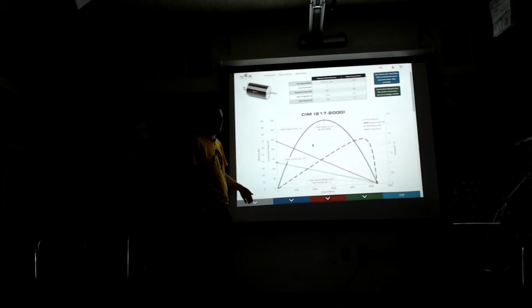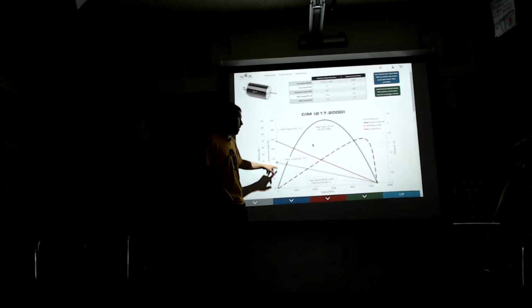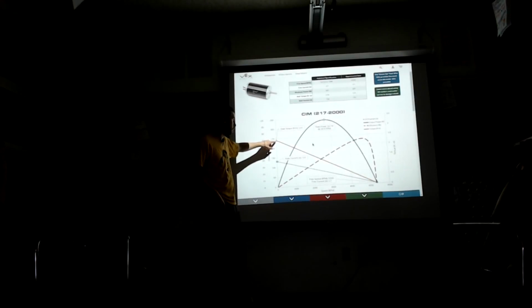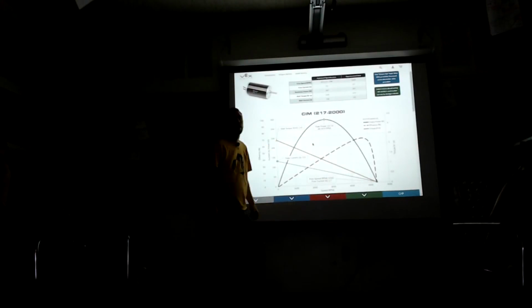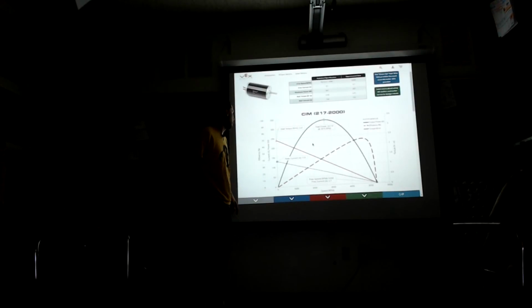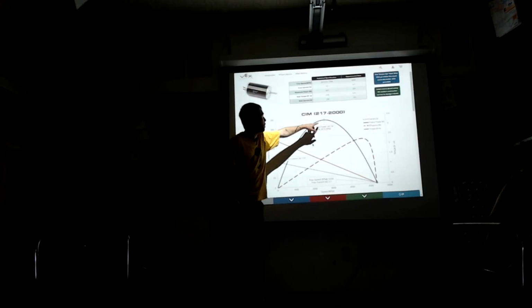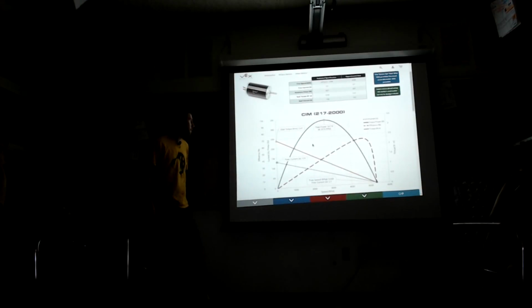As your generator is spinning faster and faster, it's going to generate more voltage. So it's going to reduce the amount of current that you can apply, which reduces the torque. So we can see a linear relationship with current. When we're stalled, we get all the torque, and when we're at free speed, we have no torque. It's a linear relationship, so you can see that here. Power is torque times speed, so you get a parabola there. A bunch of really good data here.